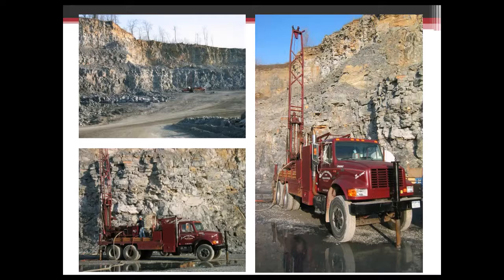Now, there are certain methods that we can use to reuse some of that water at the surface if it's coming back up to the surface, but it doesn't always work that way. Generally, when we're coring bedrock, we're using quite a bit more water, somewhere in the neighborhood of 300 to 500 gallons per 5 feet of advancement. When we were doing a lot of this rock coring that you see here in these pictures, what's not pictured there, because it was out filling up, was the 3,000 gallon tank truck that they were supplying water for us with.